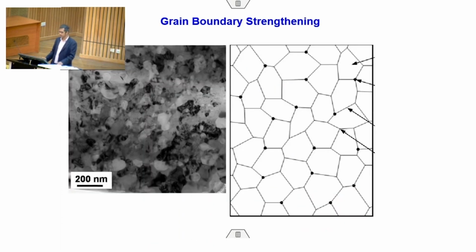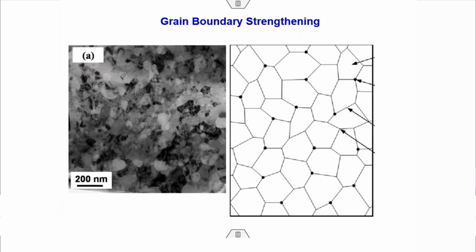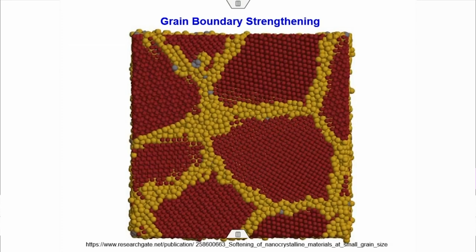Well, so as you know, in a polycrystalline or nanocrystalline material with many grains, there are so many grain boundaries, correct, a large amount of grain boundary area, and this large grain boundary area will create a large amount of pile up, and that will lead to more hardening. This is expected, correct. That is what is normally observed. Now, can you model it? Yes, it is possible to model it. It is possible to develop an equation to do that, and that equation is known as the Hall-Petch equation.